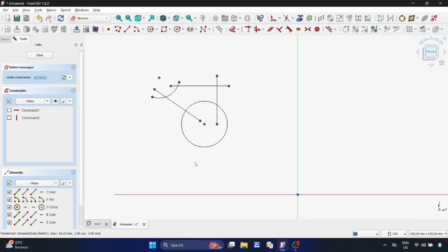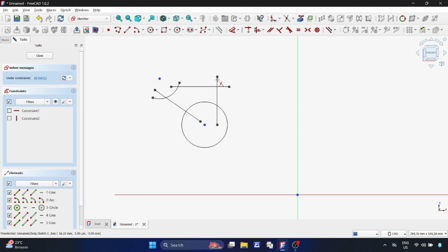Finally, this is the most frequent problem, sketch cleanliness. Lots of lines with ends that don't meet properly, creating overlaps and messy corners. A sketch like this is prone to errors. With the Trim Edge tool, we can clean this up. Just trim away these small, unnecessary segments, one by one, snip, snip, snip. And we're left with a clean, tidy sketch that's ready for the next modeling step, like a pad or a pocket.